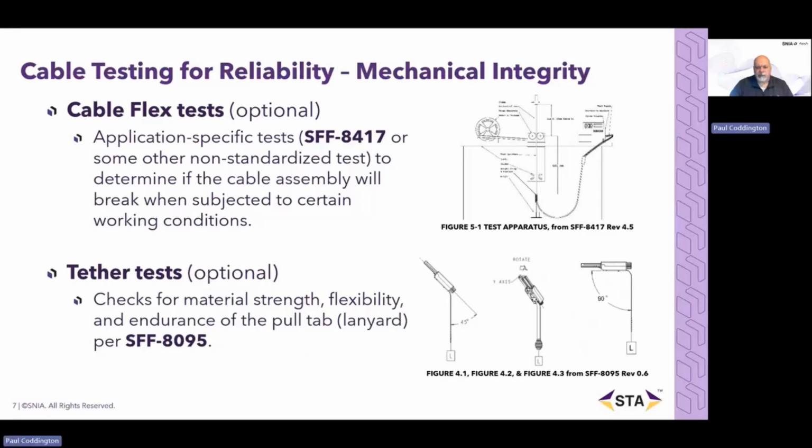Premature aging of some plastic materials can also sometimes result if the plastic compound pellets were not properly dried prior to the molding process, especially with certain plastic materials such as nylon, that tends to absorb moisture from the ambient air around them over time.